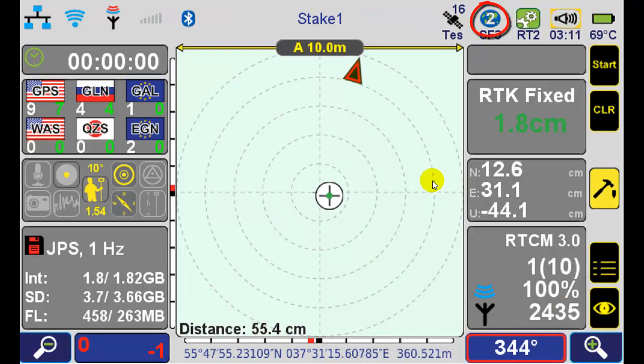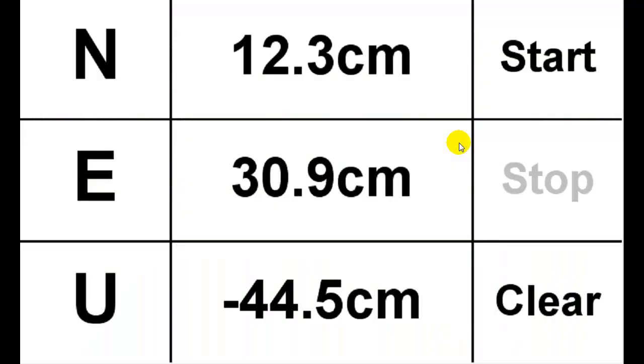The current layer shows the layer of the selected target point, and the coordinate system of this layer will be used for internal calculations. The name of the selected target appears on the top of the screen, and direction to that point is shown in the result box in the northeast up format. To see the direction numbers in larger fonts, just click the action button again, and in the summary action screen, see northeast up numbers in large fonts.